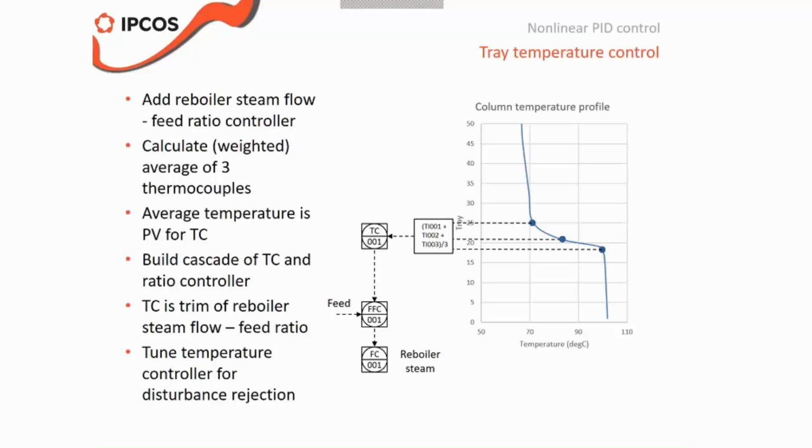10 degrees is a lot, and you always wonder what happens if I increase steam and I wait for, let's say, 20 minutes, and I see the temperature go up by 20 degrees. What happens to my top product, like an off-spec? So if I don't wait long enough to reach a new steady state, then increasing reboiler steam means temperature will go up. But before, let's say it increases by 5 degrees, and then I step the reboiler steam down again. And that looks a bit like a level controller. And that's also how you would like to tune these temperature controllers.